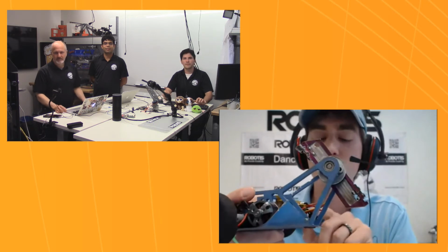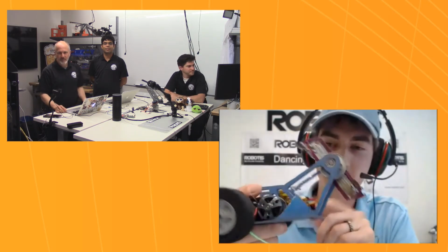Yep, just like Electric Boogaloo, this is a kinetic energy-based vertical spinner. So there are normally 2 teeth right there. That one actually broke off in its last fight. So there's a good one. This is a grade 5 titanium bar that I milled out on my mini mill in my shop. And then the uprights are a 7075 alloy aluminum. And the base plate is also grade 5 titanium. Kind of hard to tell because of the awesome paint job.